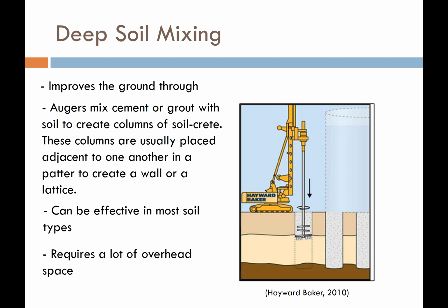Okay, another method that I've seen and used in my consulting is called deep soil mixing. With deep soil mixing, we are improving the ground through, interestingly enough, confinement. You could argue it could be other methods too, like reinforcement, but the interesting idea is that we're not really trying to get super high strength columns here.